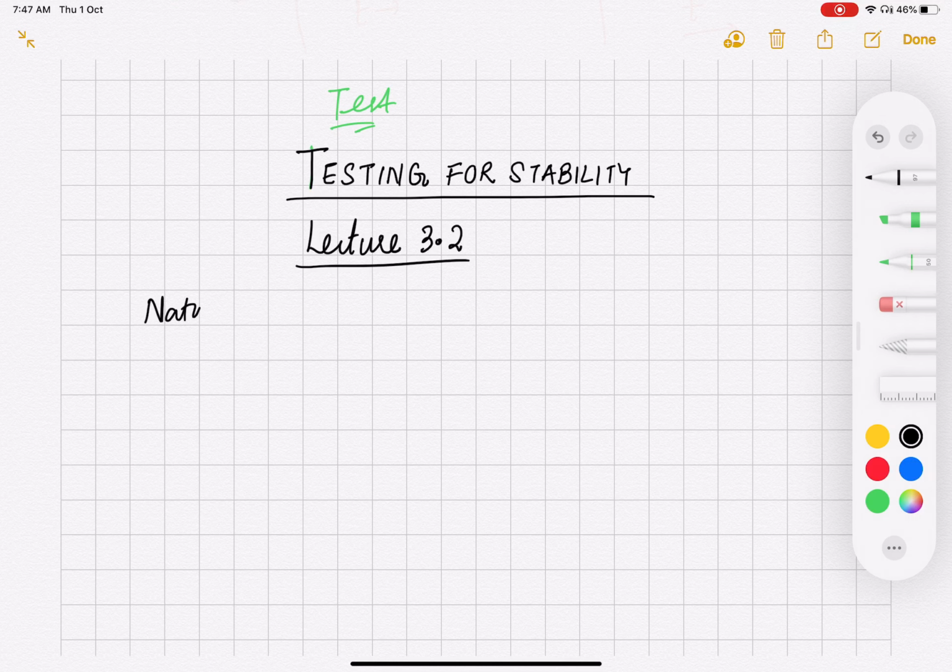Now it is not always possible to factorize a system like this, or have the poles so easily visible, right? So how are we going to test for stability? We can make certain observations. What is available to us is the characteristic polynomial, and we don't have the poles available directly. We'll have to factorize the characteristic polynomial to find the poles.